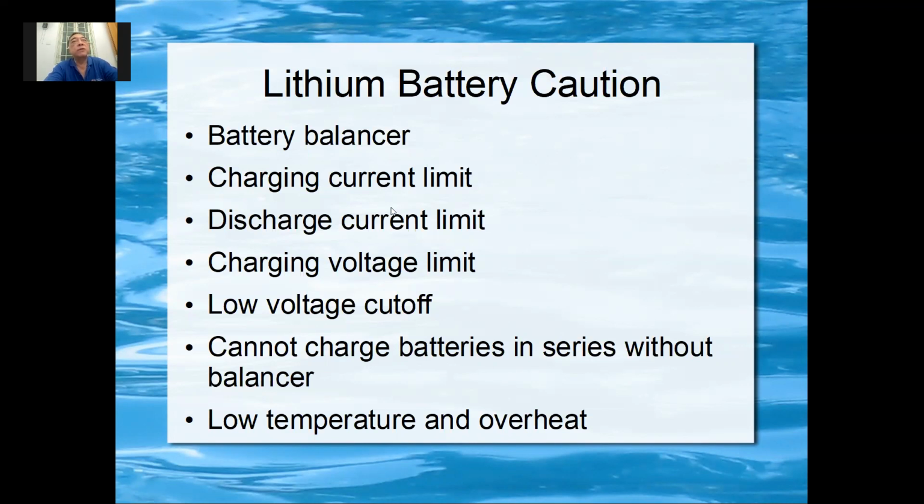Lithium ion will burn. Too hot, it starts to burn. And when you discharge too fast, dendrites will form. Dendrite, later I will explain to you what a dendrite is. That can cause a short circuit inside the battery. That will cause the battery to burn, catch fire, and you don't want that to happen when you are using it, and then the battery catches fire and you can't run away, like in the lift or when you are sleeping.